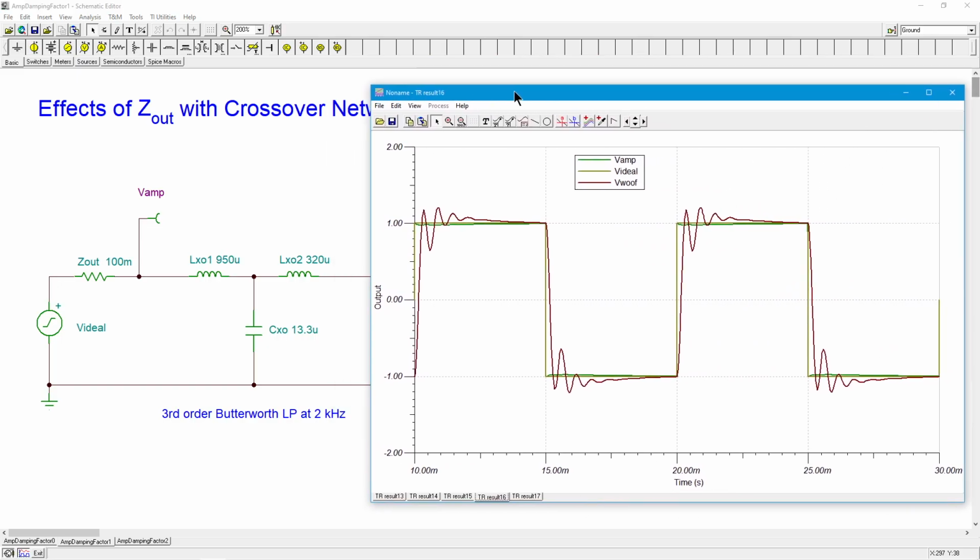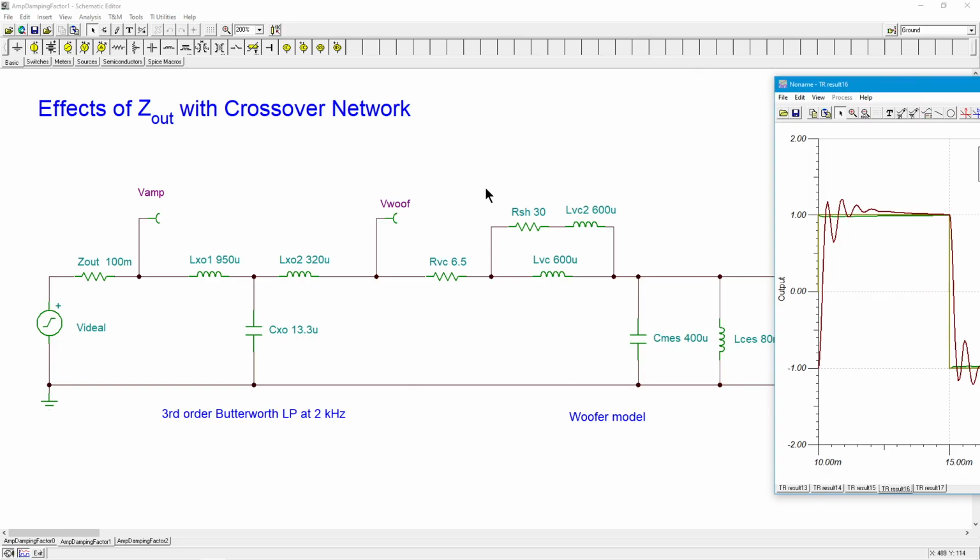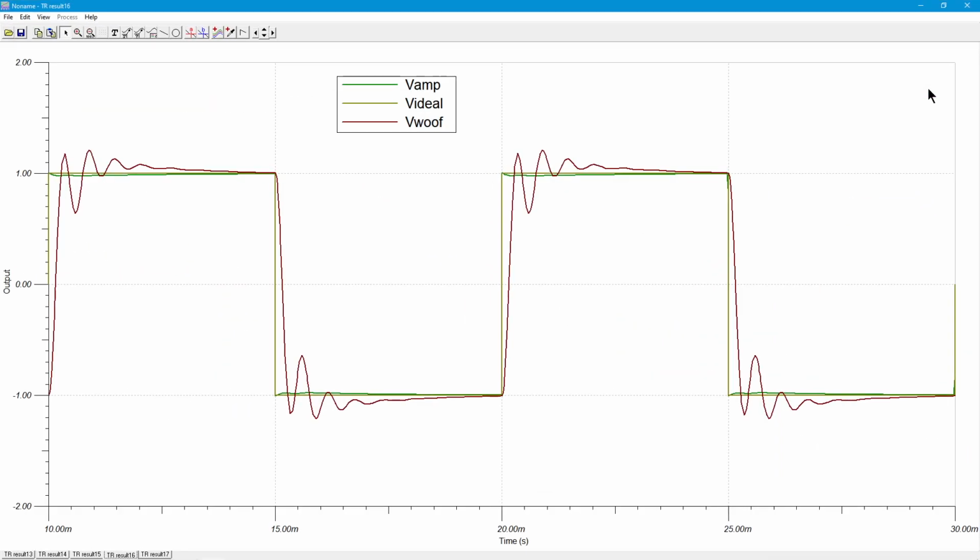Now, if you've seen some of my other videos, you know that there is a way that you can control the crazy impedance swings on here. You can do something called impedance correction. What that will do is flatten the loudspeaker's peaks and valleys, so you get something closer to an 8 ohm load. In other words, a nice ideal resistor. It won't be perfect, but it'll be much closer to an idealized 8 ohm resistive load.